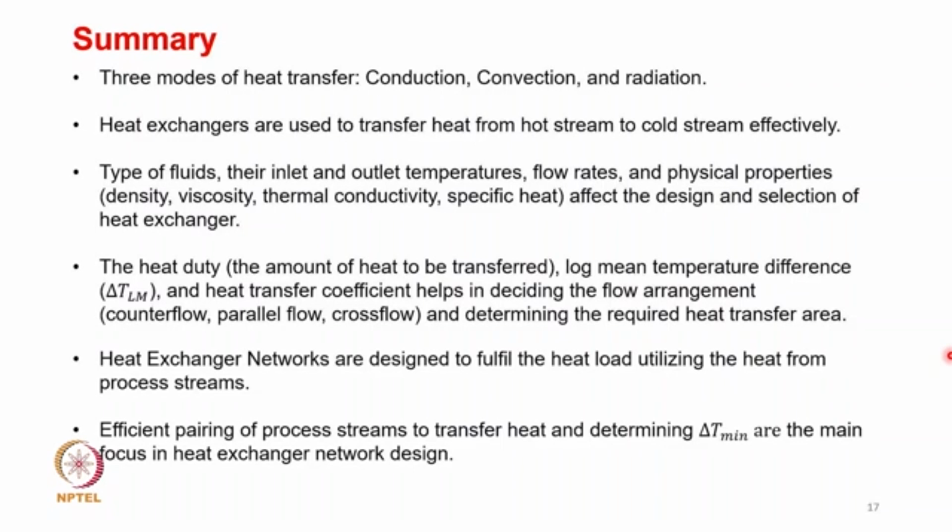The heat duty, which is the amount of heat to be transferred, the logarithmic mean temperature difference, and the heat transfer coefficient help in deciding the flow arrangement. So you need to actually pick one among counter flow, parallel flow, or cross flow. So these are the conditions that help you to pick one among those, and of course, in determining the overall heat transfer area.